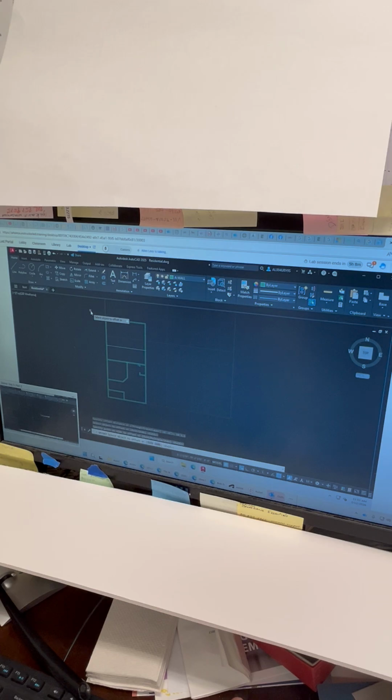If you remember, the default distance that we used during our practice was, start your offset command. Your default distance was 3 foot. Go ahead and hit 3 foot and hit enter. All right, now select the bottommost line of your south wall, the bottommost line. Move your mouse above it. Now that's not 3 feet. That's 1 foot 6, if you remember. Anytime you enter on your keyboard.